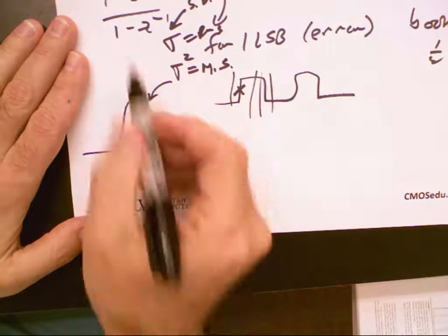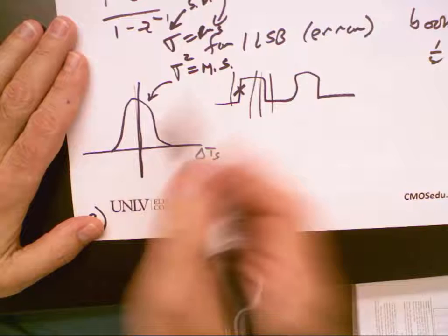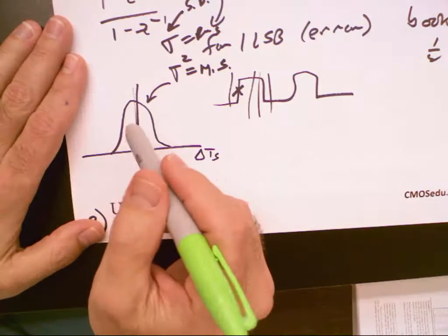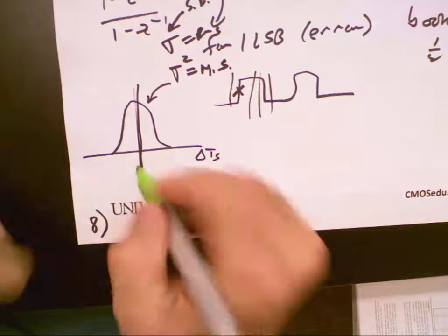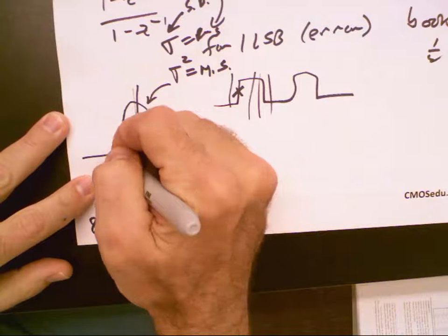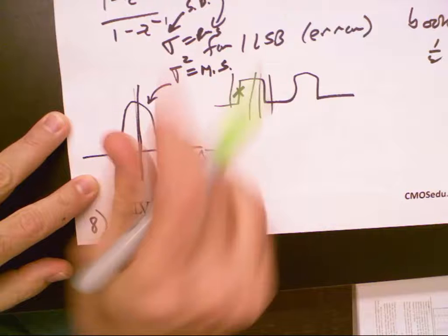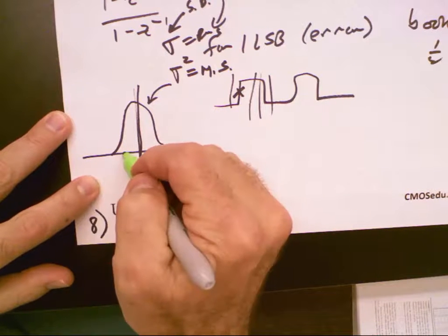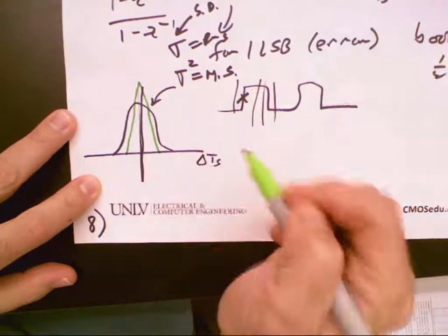When you run these random signals through one of your low-pass filters like this and you start averaging points, what it does, not to the spectrum, to the probability density function, is it reduces the distribution.